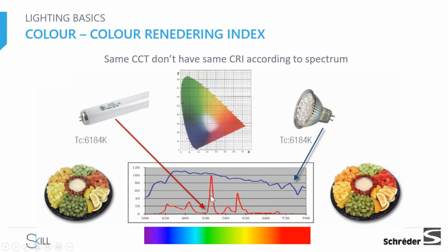So I hope that this was clear for understanding in a different way how to look at the color rendering and the color temperature. Of course, there is a relation also. By initially looking at the spectral distribution, you'll be able to identify that this will be high or low color rendering, and also after time maybe you'll be able to expect that this will be warm or cool or neutral white.